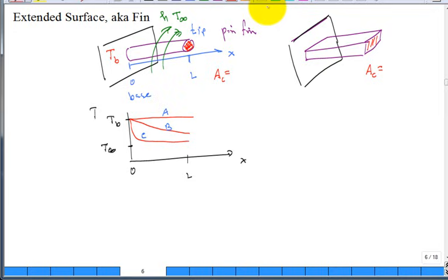For the rectangular fin of length L, moving out from the base, of width W, and of thickness T, can you tell me what the cross-sectional area is? Is it the product of W times T? Yeah. All right. Go back to our pin fin. What is the cross-sectional area? Pi r squared or pi d squared over 4. If you like radius or diameter, both are acceptable.